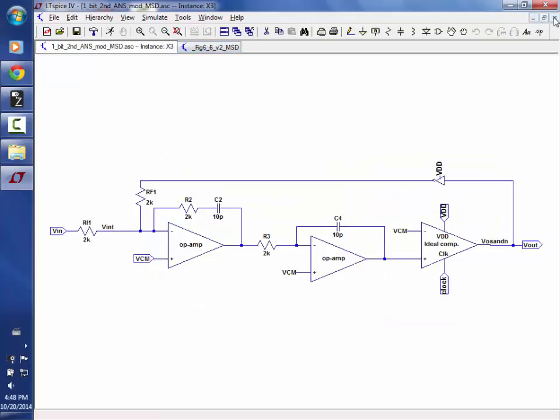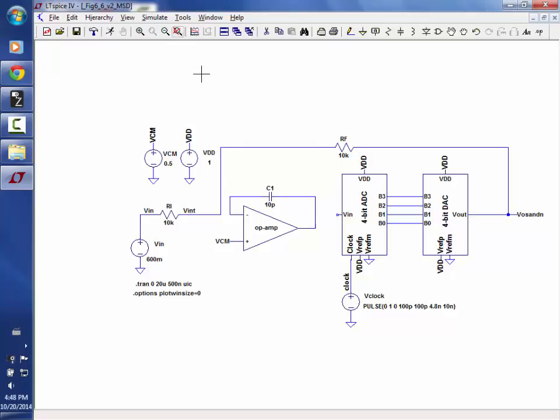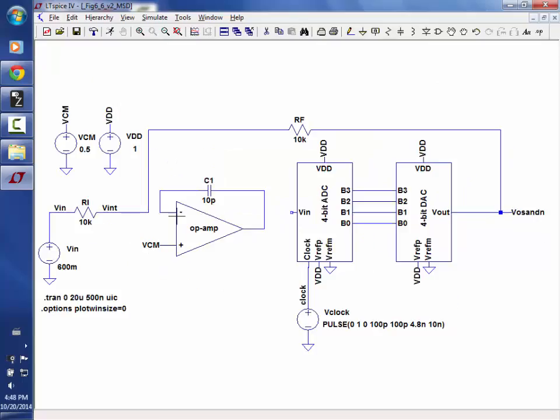Okay, so the big difference here is that the error that I have in the passive modulator is going to accumulate in this guy. I used 10 pico before as well. Now the output of the integrator is going to keep rising until the output of the DAC changes. In other words, Vint goes to 0. So if there's a difference between this voltage and this voltage, there's not going to be a dead area. It's going to just keep accumulating until it forces this loop.